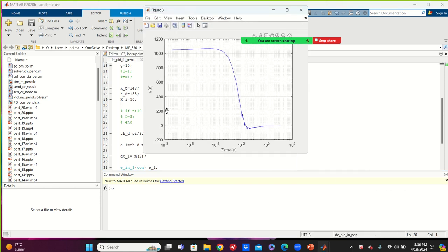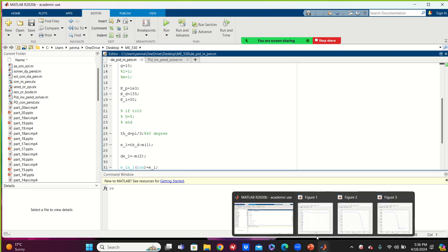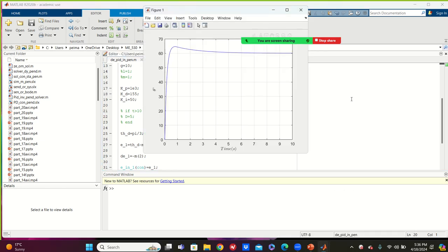If you remember it was 70, 80, but the transient response settling time is much higher, 50 seconds, like that. So that's the trade-off. You as the designer of the controller have to decide. If your actuator can't tolerate that, based on the requirements of the system, you can tune this. Now it goes to 8 seconds.